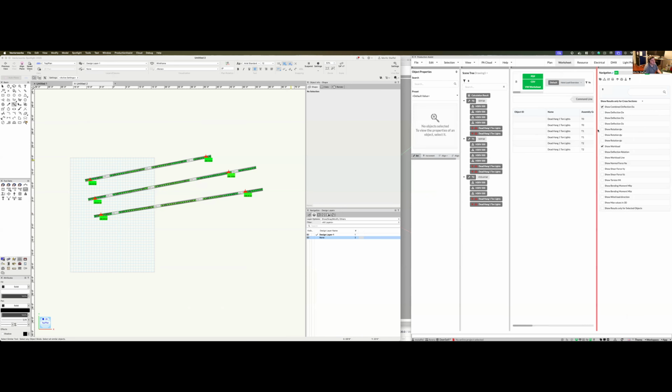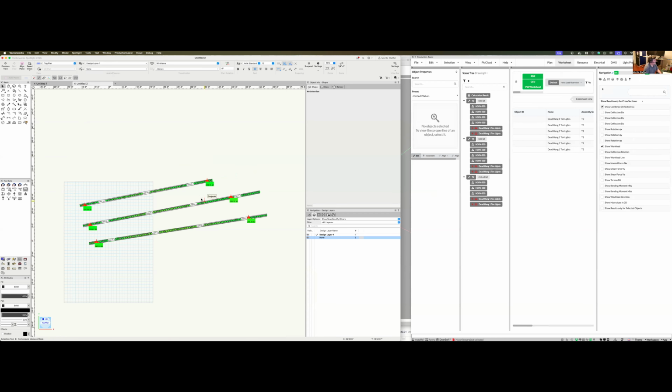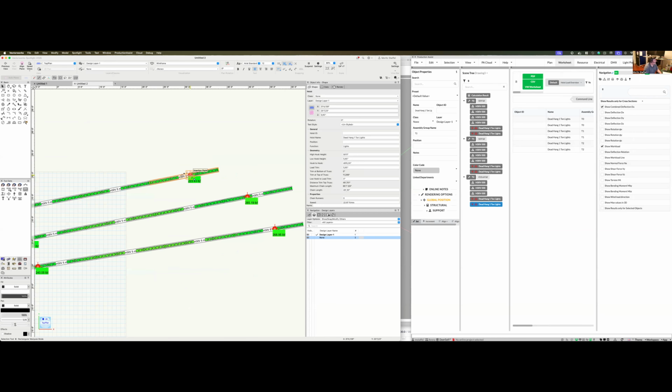Simply navigate to the section in the Production Assist panel dedicated to calculation results, where you'll find a toggle button for influence lines. When you activate it, colored lines or gradient overlays appear on your drawing, visually representing how loads are distributed along your trusses. This real-time feedback is invaluable for verifying that your design is balanced and safe.